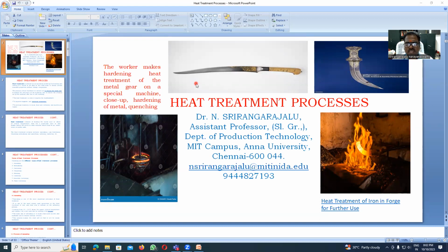So what is meant by heat treatment? Heat treatment is nothing but heating the material to the required temperature, then holding for some time. After that, you make a cooling, slow cooling or fast cooling. Based on that, you will get the required hardness.